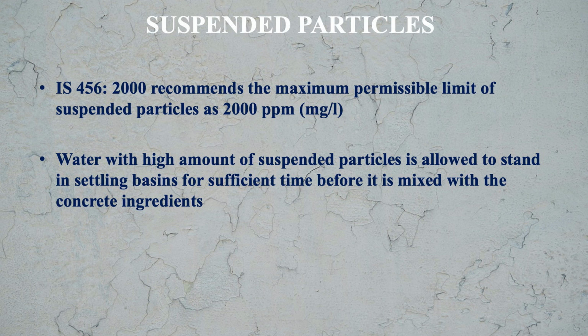Water with a high amount of suspended particles may be allowed to stand in settling basins for sufficient time before it is mixed with the concrete ingredients.